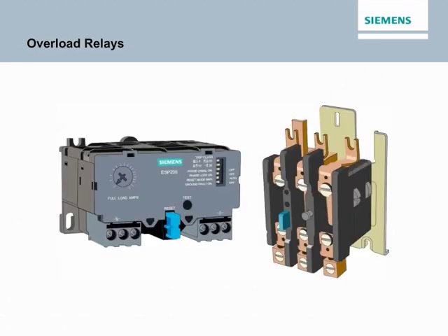Contactors are used to control power in a variety of applications. When used in motor control applications, contactors can only start and stop the motors. Contactors cannot sense when the motor is being overloaded, and they provide no overload protection. Most motor applications require overload protection. Although some small motors have overload protection built into the motor, more commonly, overload relays, such as the one shown in the accompanying graphic, are used.